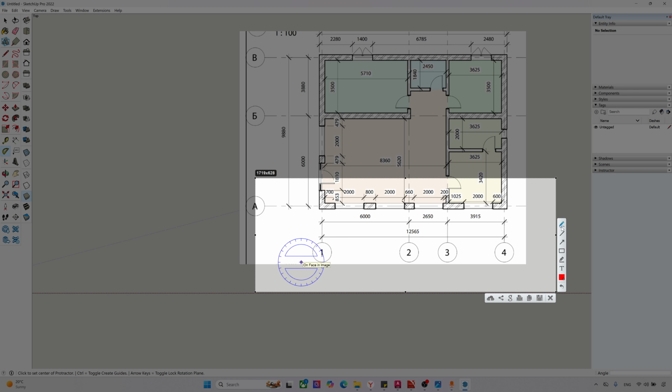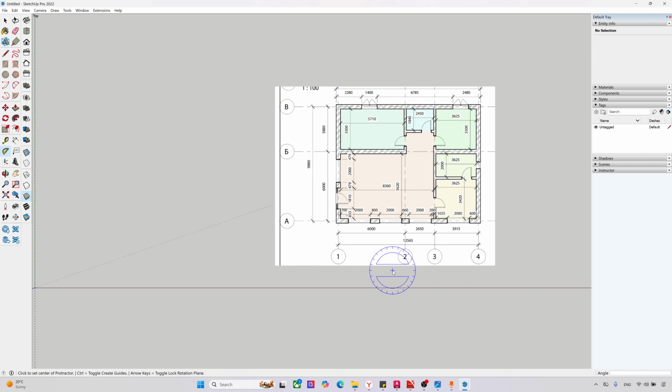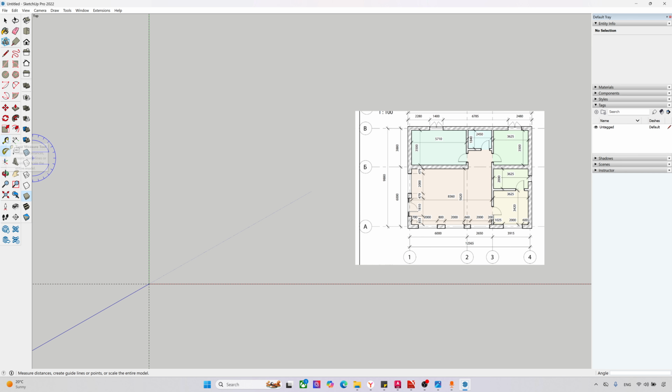Going to create others. First, I'm going to create the distance, make some kind of corners, not corners, let's say vertices or splines. Going to create such vertices first and then copy the construction line that we created at first. To make that, I'm going to use this tape measure tool, going to the origin from the 0 point and just typing my dimensions.